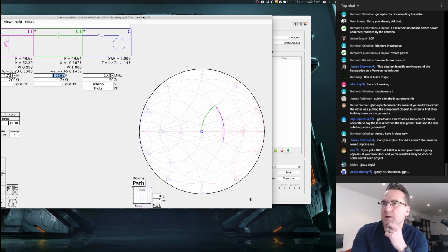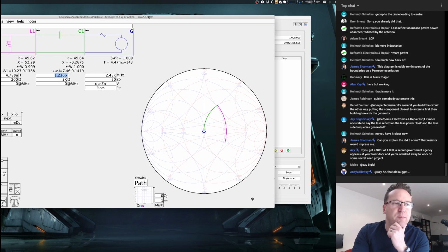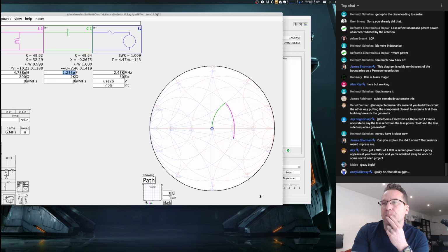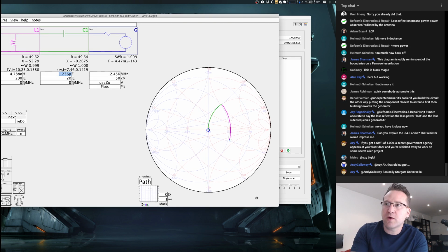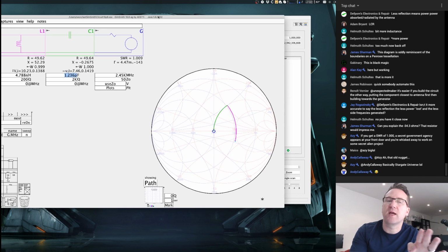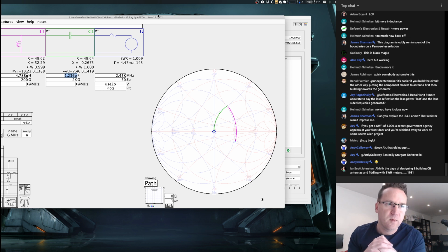Possibly. Either that or maybe my cable wasn't on. No, I checked my cable last time. I beeped it out. Yeah, so the ground plane was the issue for sure. That's all fixed now. And it shows me that I do need a matching network, that I can't get away with no network, unfortunately, which is a shame. It's less components. Well, let me rephrase that. I could get away with no matching network if I was happy to ship the boards with not as good Wi-Fi as I'd like, which obviously is not something I really want to do.